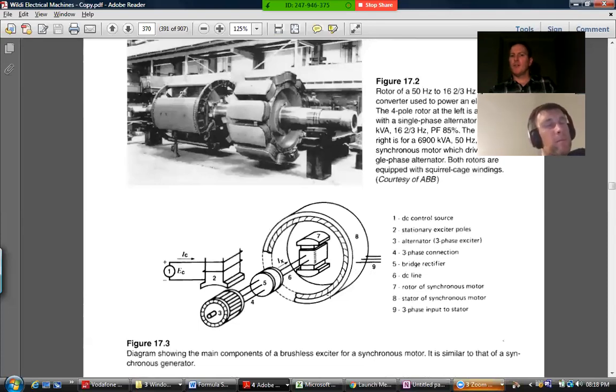And you'd feed that rectified current into this thing via those 2 slip rings. So in that case, there wouldn't be a little mini generator, either a commutator and slip rings or a generator and rectifier. You would just feed in current extracted from the grid through a rectifier, through the slip rings, and you wouldn't have this thing at all.